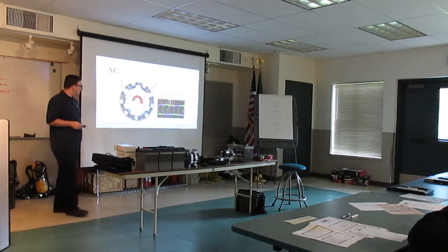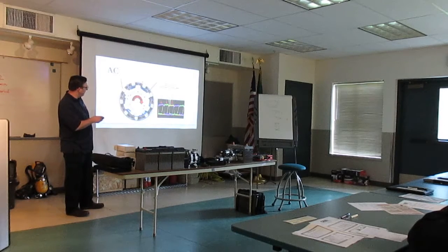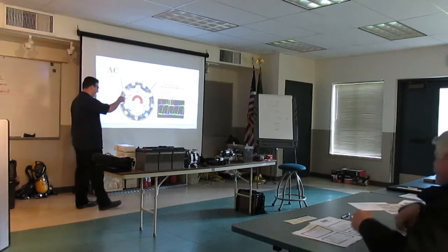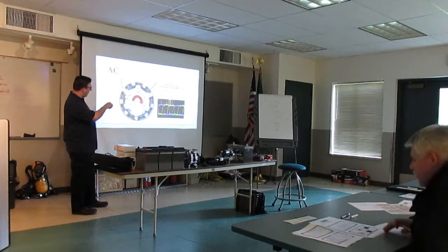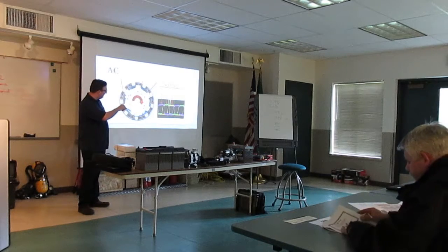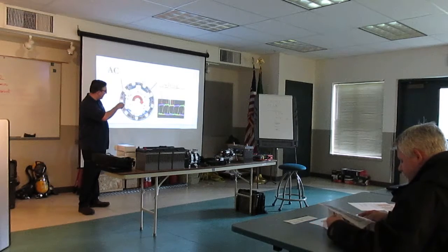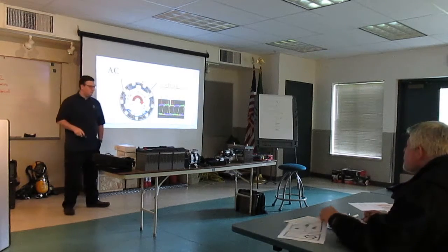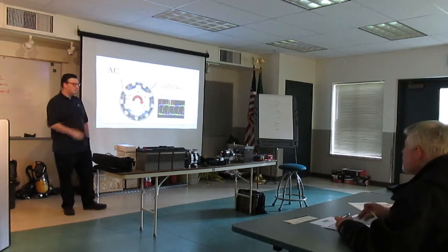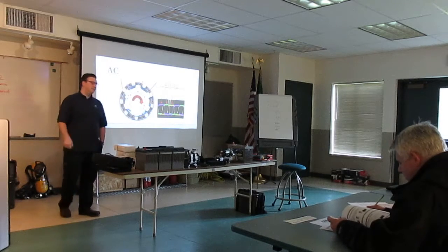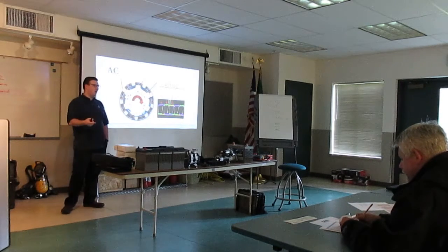Now, speaking of your AC, there's our AC pattern, and that's our ripple. Here I have all three phases wired up and showing. And as each phase comes around, as we go up and down, those peaks as we come down and come up create a ripple. Now, does that look like a bad ripple pattern? No, because it's consistent.